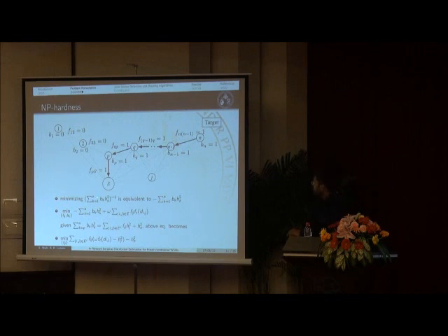Minimizing the weighted sum of distortion as well as the cost can be written in this form, where Fij is the network flow from sensor i to j. So Fij could be 0 or 1, because it is an integer optimization problem. And the cost function is proportional to d_ij raised to the power alpha. So in this case, we have to minimize the weighted sum of the total distortion and the total cost. Here, omega is the weighting factor that controls the quality of estimation based on the total power budget.